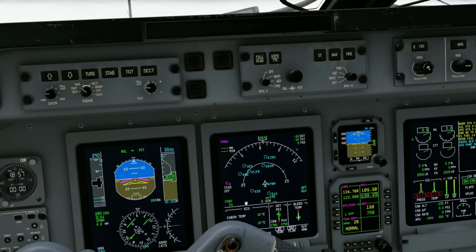Stab disables stabilization, rather. The radar is stabilized so that when you select angles, they are in reference to the horizon. So when you see something saying 3A, right now we have 3 up, 3 above. That's in reference to the horizon, not to the aircraft.